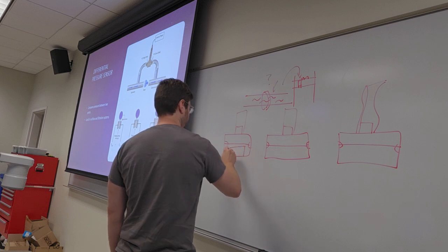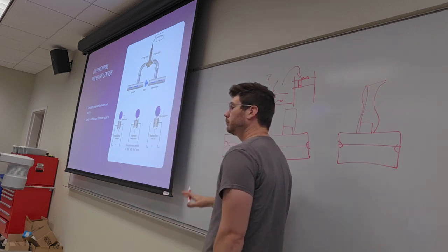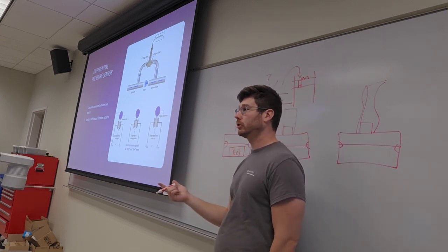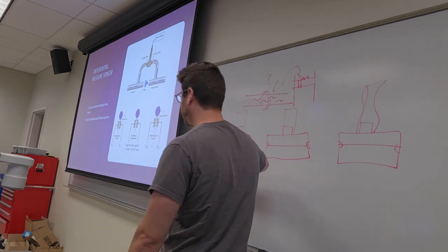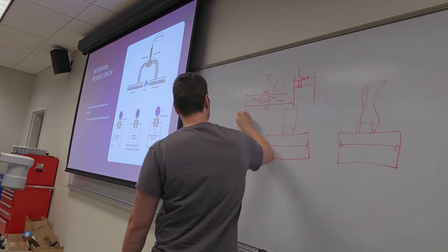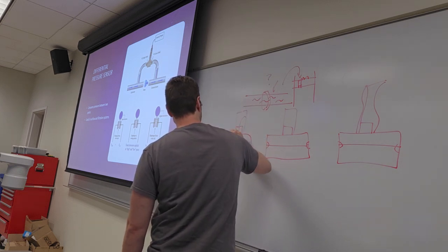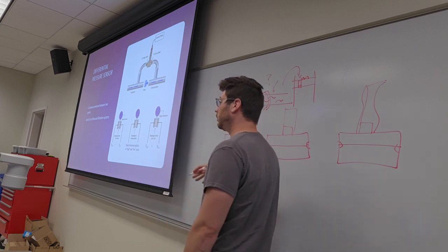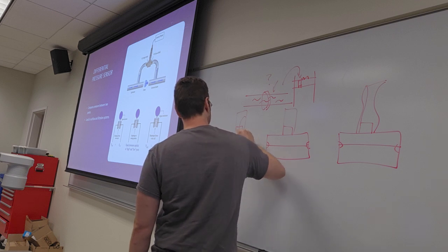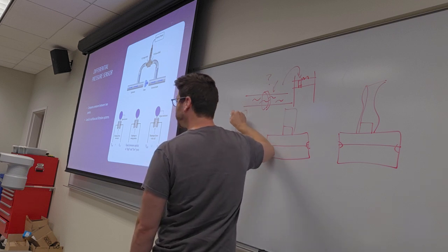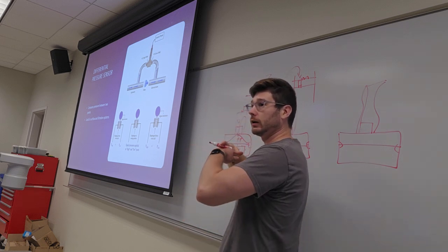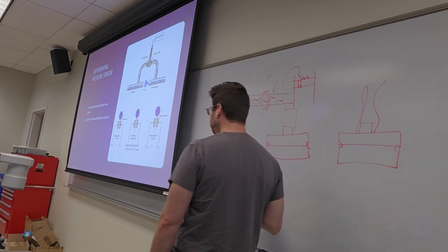Sometimes it has a sealed reference gas, some pressure that we always want to compare against. You know, absolute vacuum, ambient pressure, whatever. If we're at the bottom of the ocean or in space, this reference volume would always give us the same pressure. It's only what are we comparing that pressure to? And that pressure will cause this membrane to bulge out or bulge in accordingly. Okay, you guys see that if this bulges out, this means that this pressure is greater than this pressure. So we have a negative pressure on our inlet. Same thing for the positive, right? We would get a positive deflection of our membrane, okay?